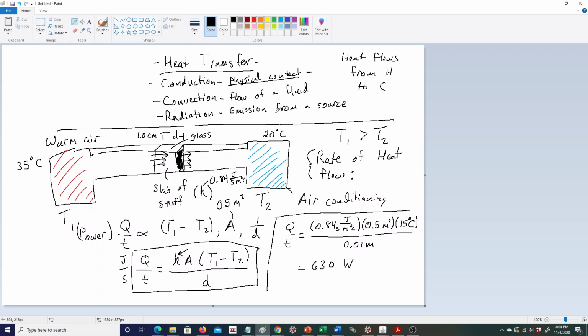Hot things like to rise, cool things like to sink. And so the cooler water at the top of the pan will then be forced downward and sink, and it will then heat up. And the hot water that had been transported to the surface cools down slightly with the contact with the air, and this process just keeps continuing. The hot boils up from the bottom, the cool sinks, and you get this kind of circular flow inside the water. That's what the bubbling actually is.